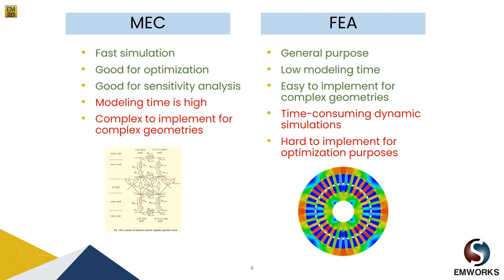But this situation is not true for the induction motor. For the induction motor, the geometry is regular and the flux line pattern is regular, and this equivalent circuit is good for analyzing the induction motor, right? Because the prediction of the flux lines inside the rotor yoke, stator yoke, rotor teeth, and stator teeth is not too complex.